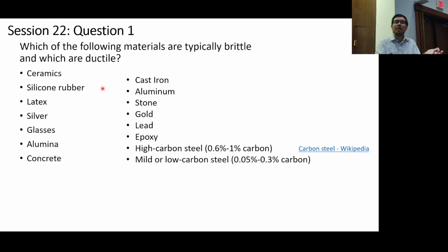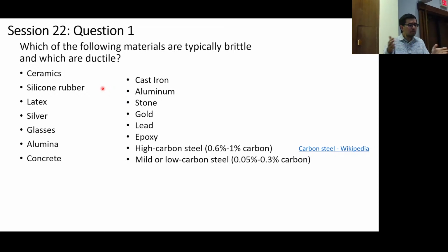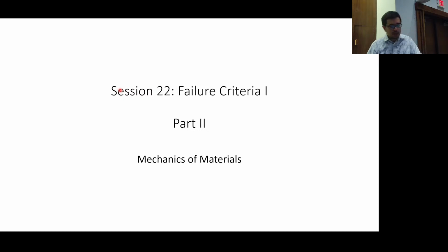So, say you had some type of semiconductor process, or not even semiconductor process. You just had a surface that's shattered, whatever it is. It will replicate that detail very, very intimately, down to a couple of nanometers, or 22 nanometers, something like that. Okay, so because of its low surface energy, it gets into every nook and cranny, and it can also come in pretty low viscosity, still higher viscosity than water, typically, but silicones, as you know, they have a lot of different viscosities. All right, so this material, it can change your life. All right, as many materials can.